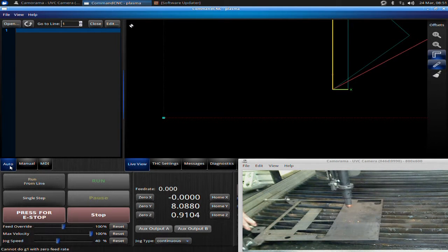So a couple things about these stops. They're fully adjustable, and you will want to fine-tune these to the actual motion of the torch. What I recommend is get a known straight edge, set it up against these material stops, and then run the torch down the edge of that straight edge and determine, are these stops relative to the motion of the torch in the right spot. If they're not, adjust them in or out. Okay. You can also adjust the angle of these stops so that they'll catch more of the plate, or you can rotate them lower.